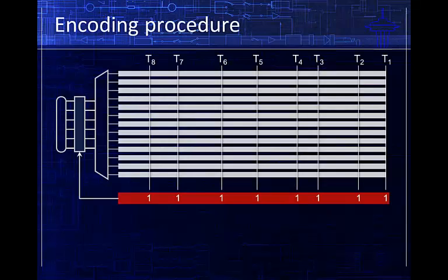With a given test template, ATPG generates a test cube that is consistent with the definition of scan segment. That means that in one segment there can only be one polarity of logic value. There might be a couple of scan cells with that value specified, but all the cells in a segment must have exactly the same value and exactly the same corresponding Boolean equation. If in a segment there is at least one value specified, we move it to the beginning of its segment, and only these values need to be encoded using the input variables coming from the decompressor. Any additional values are sustained by the hold register and corresponding zeros in the template register.